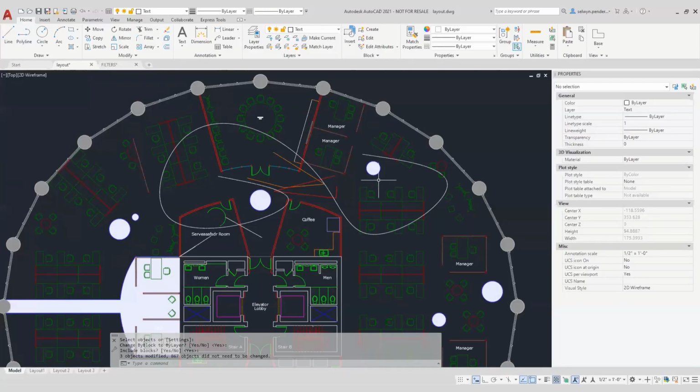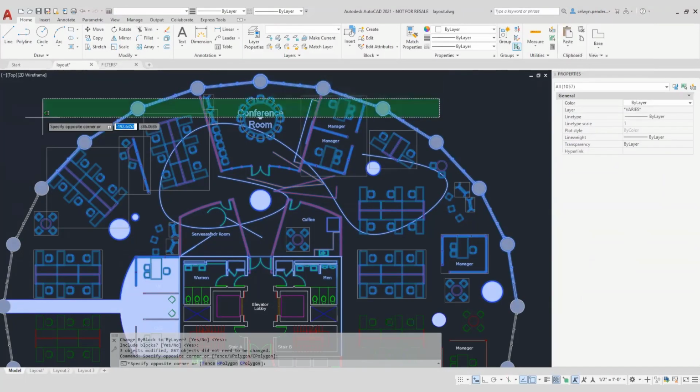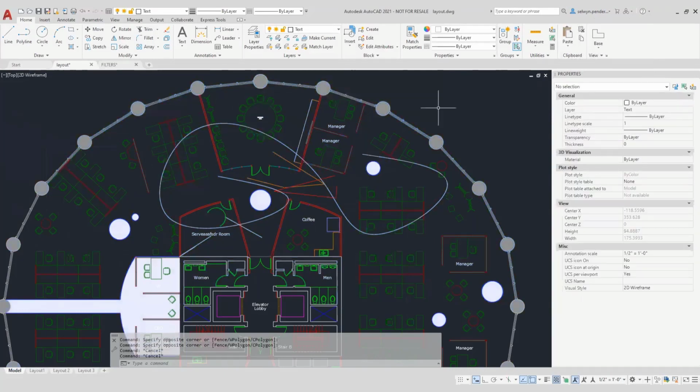It's normal practice to draw by layer, but sometimes it depends where you are. Sometimes you have to assign a color and it doesn't always work the way you want. So if you need to go through and change some objects to by layer, that could be the easiest way. Or you select and you come over into the color here and we change it to by layer here. So really, it's up to you how you do that sort of thing.